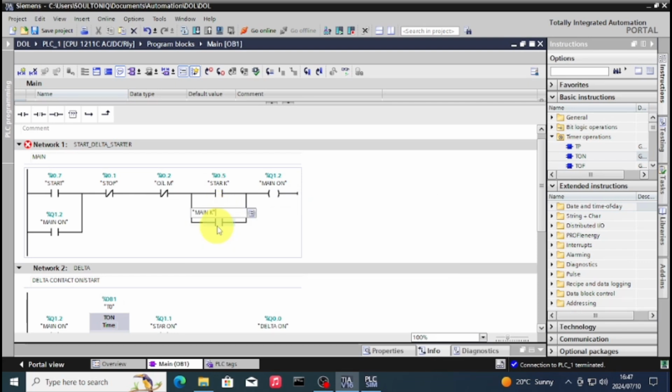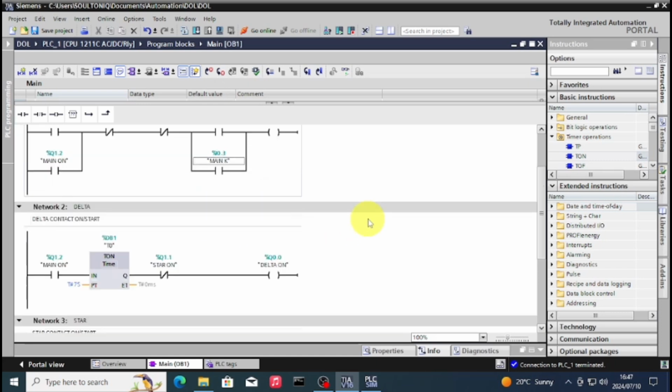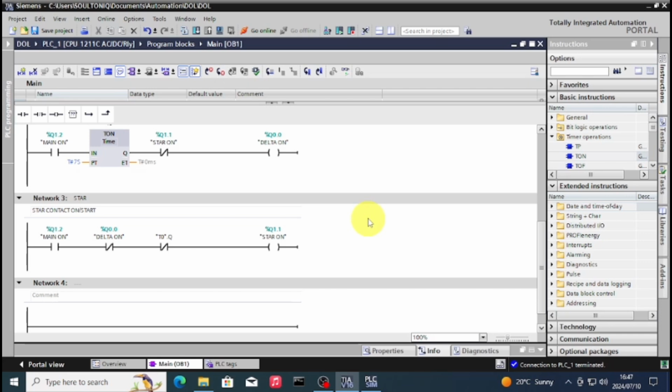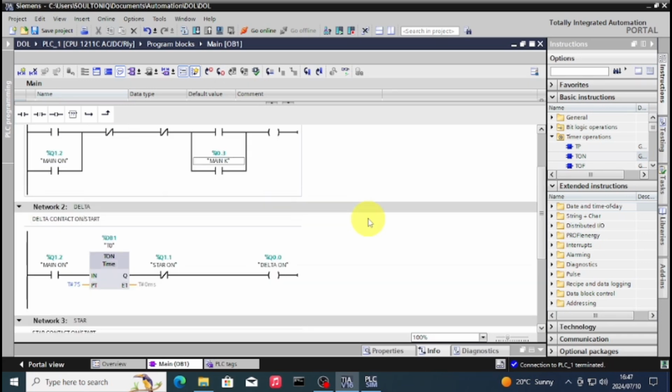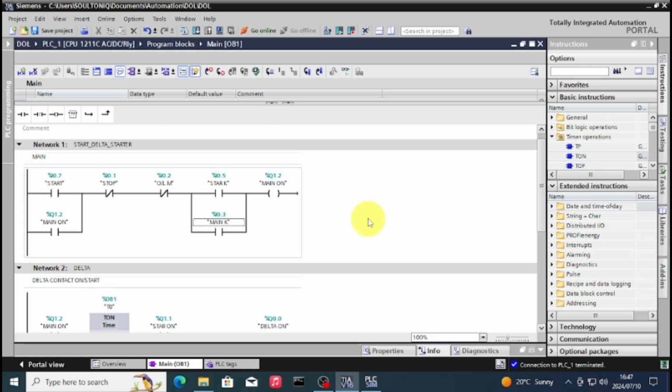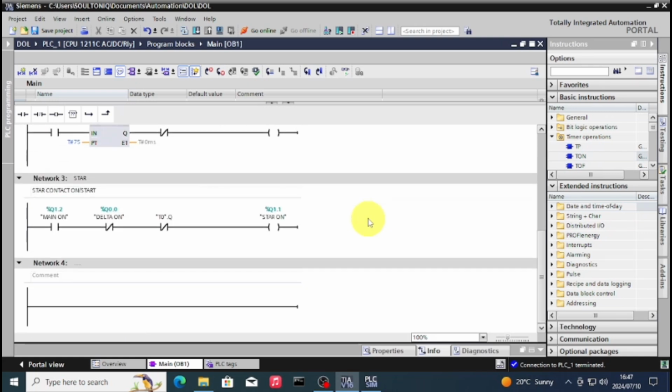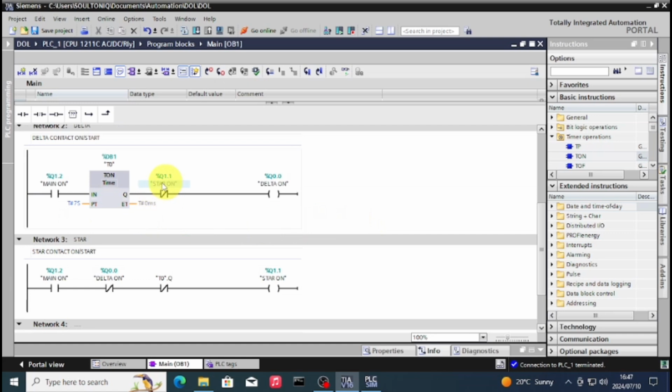So as you can see on the wiring diagram, the star should start first, and then as the contactor comes on, the normally open contacts will close. That way we have wired it there. Then it will switch on our mains. And then when our mains are also closed, the normally open contact on our mains will energize and close, which will keep our mains running.